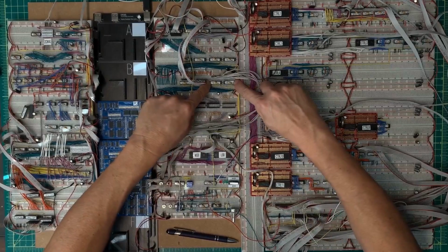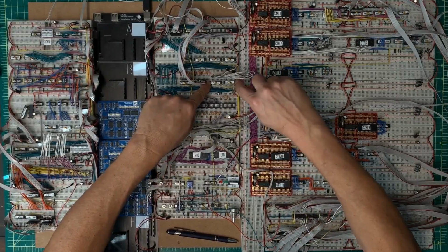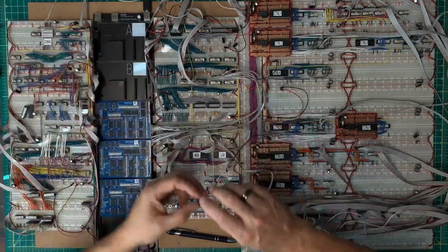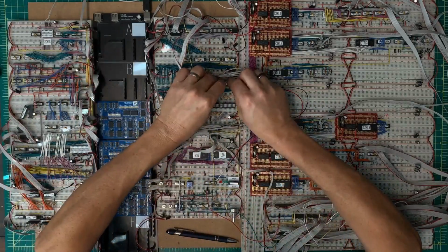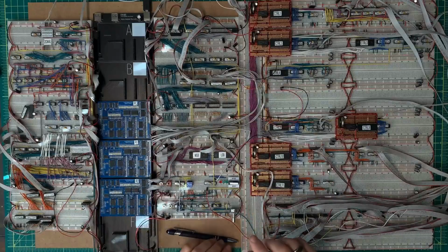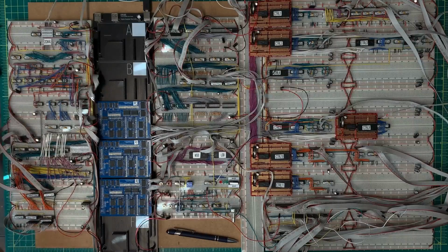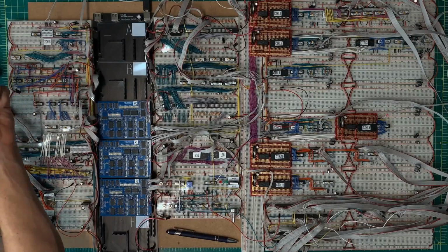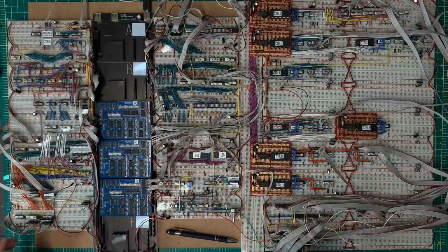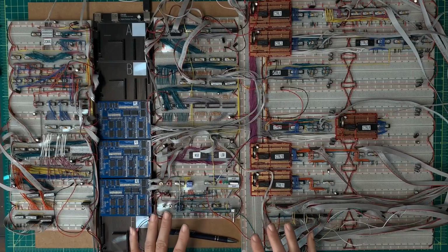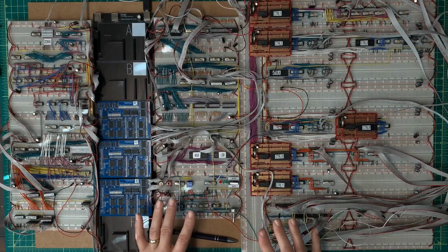Finally, coming off the fetch register, I have asserts out onto ALUB, and these are also LS logic, and I want to replace these with HCT logic so that I can properly drive both the LS and the HC logic in circuit. These are for the latch on the output, and I'm going to set those aside for now until we get voltage settled and under control. All right, that said, let me get these changes made. We'll come back, we'll give it a test and see where we landed.